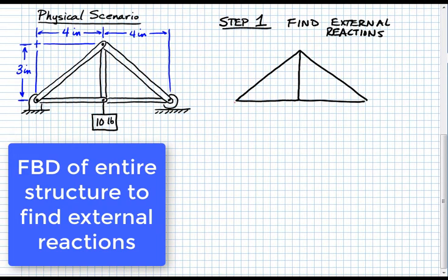We're going to understand that that's all one rigid structure that is not moving one piece relative to the other piece. The reactions that we have over here, we'll call this point A. May as well label all these points, A, B, C, and D. The reactions that we can have at A, actually we have two components of reactions possible at A, and the reason why is that we have a completely pinned joint there at A, so it's not allowed to move in either direction. So we'll put those on there. We'll call this RAY, and this we'll call RAX.